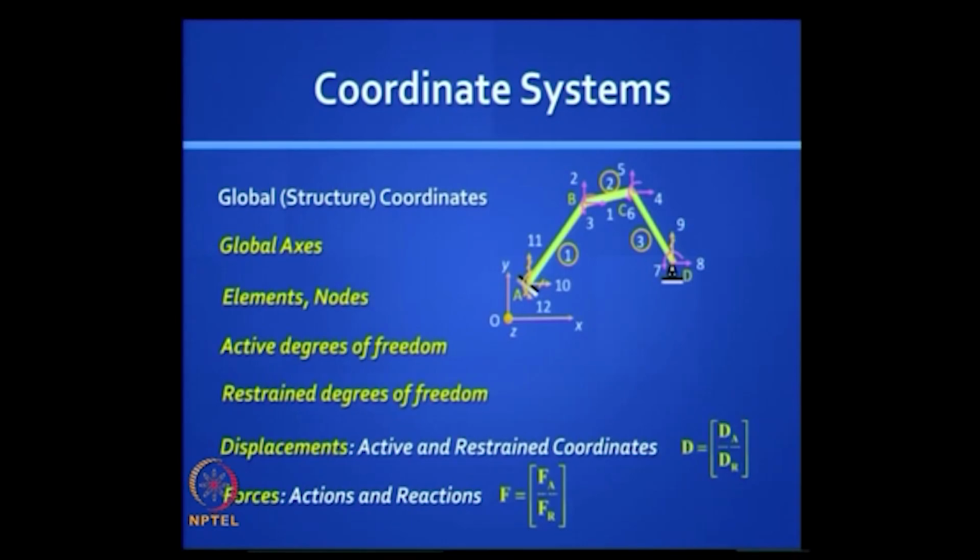So you have FA corresponding to dA, and it is exactly where you restrain displacement that you get reactions, and luckily for us R also stands for reaction. So FA, FR constitute our force vector in the global picture, and dA, dr constitute our displacement vector in the global coordinate system. Does this make sense?